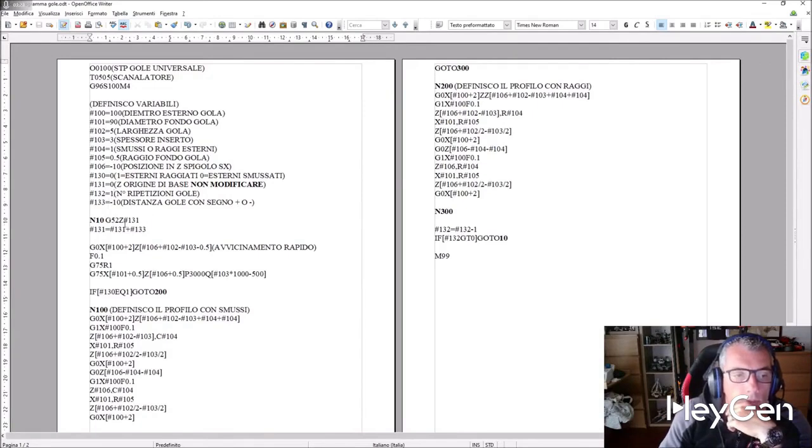After that, I'll set my origin by establishing an origin shift, which will initially be a shift of 0 mm. Under my origin shift, I'll modify my 131 by adding the origin shift to it. So, I'll set a safety distance, a rapid distance of 100 for the outer diameter plus 2, and Z will be a count that ensures there's 0.5 mm of excess material on the right side. Then, I'll use the macro for radial grooves, setting my parameter 106 as Z increased positively by 0.5 to leave 0.5 on the side, and a bottom groove increased by 0.5 to leave 0.5 of excess material at the bottom.